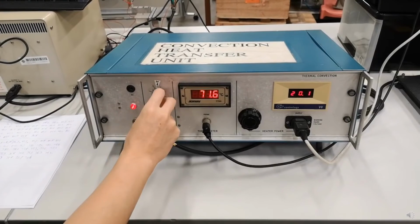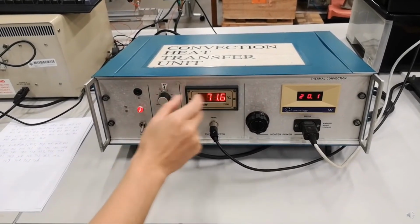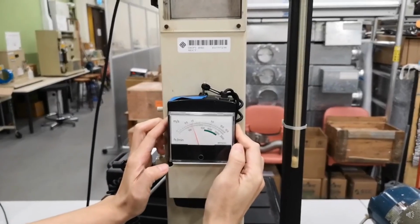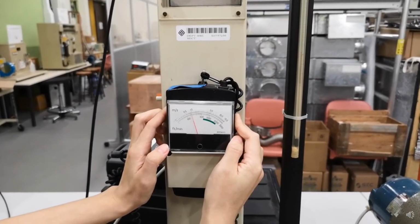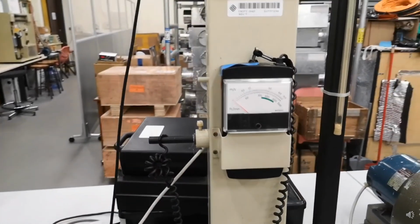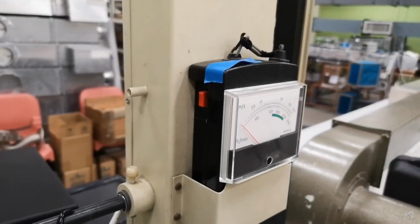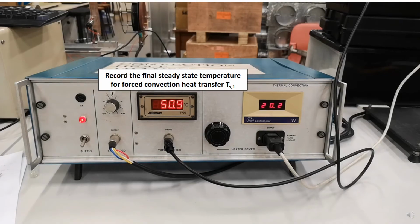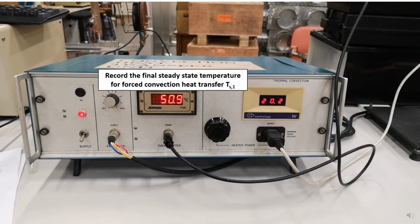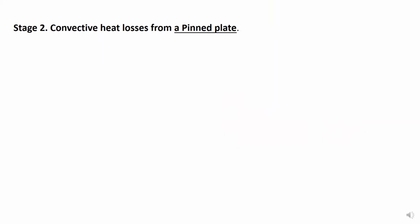Well, next we need to set the fan speed to an air velocity of 1 meter per second. We can check the velocity by using the anemometer and pushing the button on the anemometer. We can see the velocity in the duct. Then we need sufficient time to record the final steady state temperature Ts1.